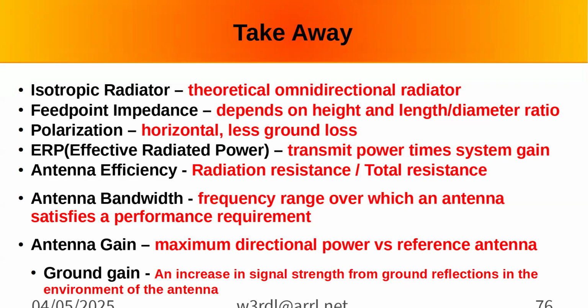Remember that question from a couple weeks back? If you increase the diameter of a conductor, what does it do to its electrical length? I actually found the answer in the latest ARRL handbook. There's a little paragraph about it, and it says kind of what I thought. The capacitance increases faster than the inductance, so it becomes more capacitive and changes the velocity factor.